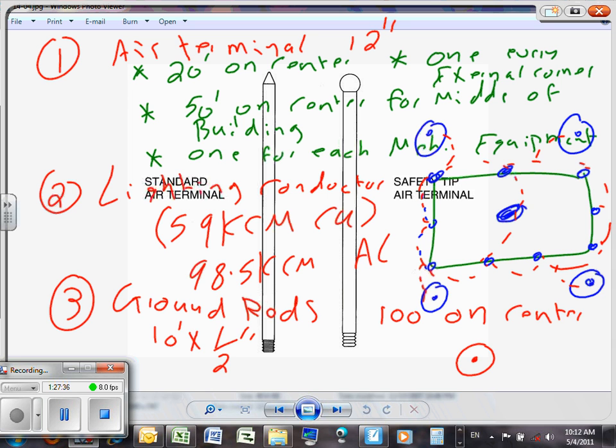And please keynote them. So right next to the ground rod, write the ground rod size. Copper, by the way, this is copper. The ground rod is CU, copper. So it's going to be 10 foot. So type, Brooks, you're going to type right next to it, 10 foot by half an inch ground rod copper. That's what you're going to do. Or annotate or whatever. Any question, guys?